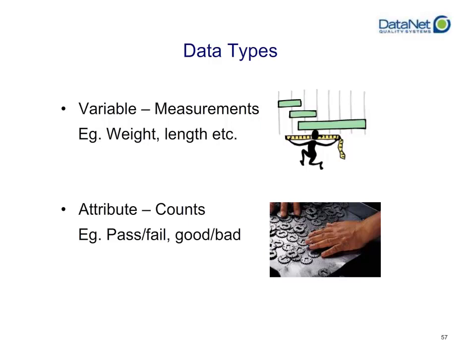It's anything that you can measure with a number, things like length, width, height, viscosity, volume, depth, anything that you can take some sort of measurement instrument to and put a measurable value on. That would be variable data. Now, if you have data that is statistical in nature but can't necessarily be recorded in the form of a measurement, things like true or false, pass or fail, things that are qualitative in nature, that would go into attribute data and would be recorded with attribute type charts.